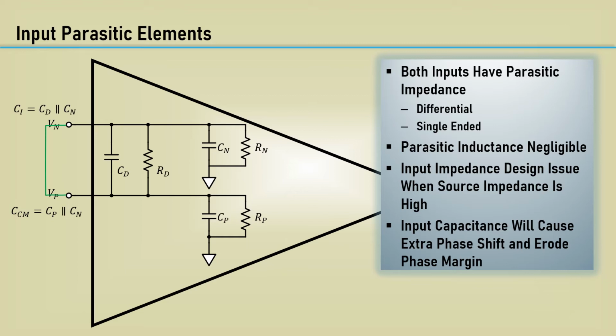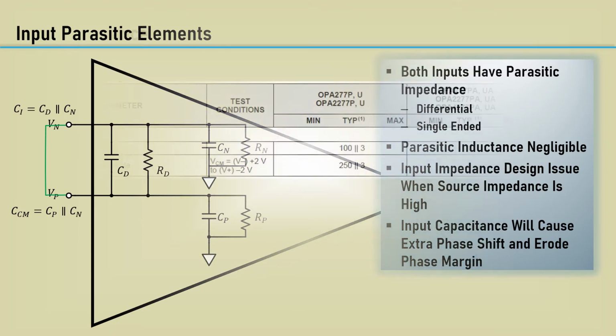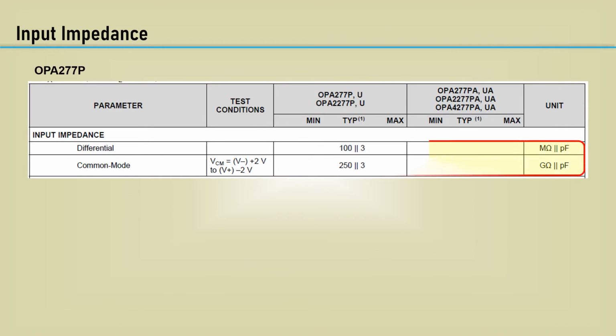Input resistance is the resistance between the input terminals with either input grounded. The differential input resistance is the small signal resistance between the two ungrounded terminals. Usually, the input impedance is specified as a parallel combination of input resistance and input capacitance.